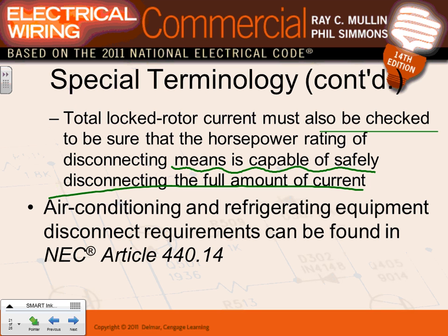If it's not horsepower rated, Jeff, you know what happens? It will explode in your face as you open it. And guys, we're not talking about 1 horsepower or 2. We're talking about 400 horsepower motors, 500 horsepower motors. You go to disconnect the circuit breaker, and it will explode in your face if it's not rated to interrupt this energy. Any comments, guys? Any questions?